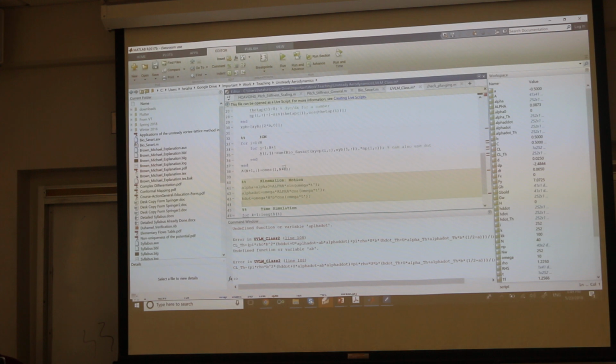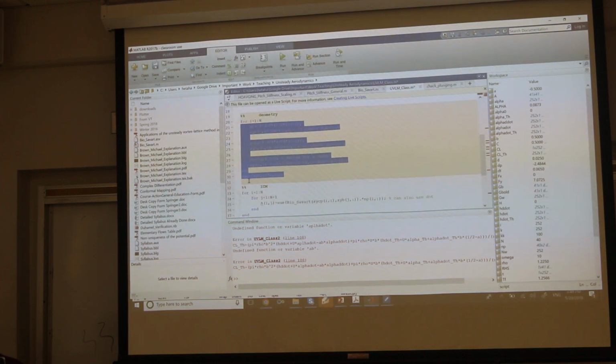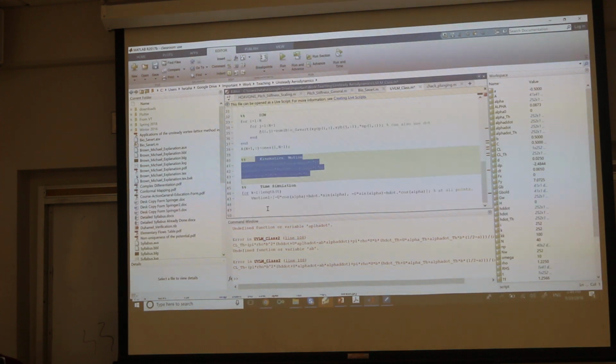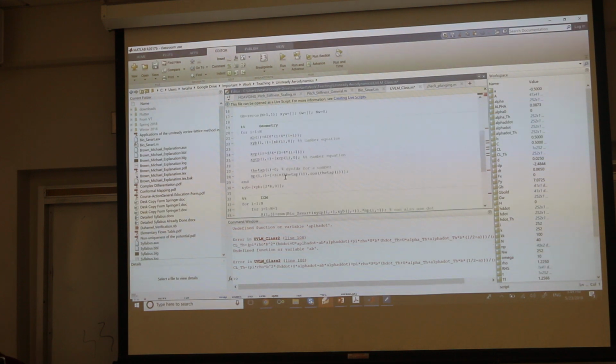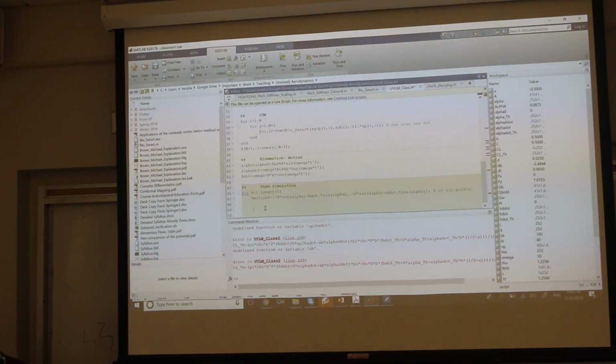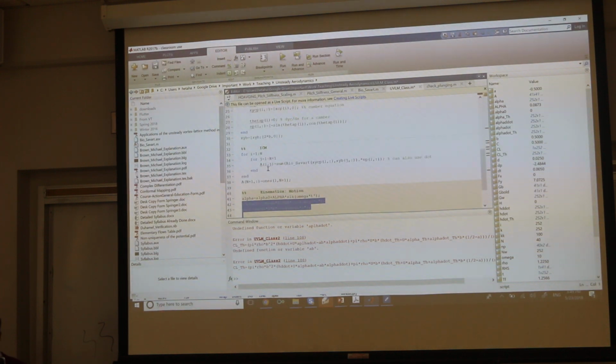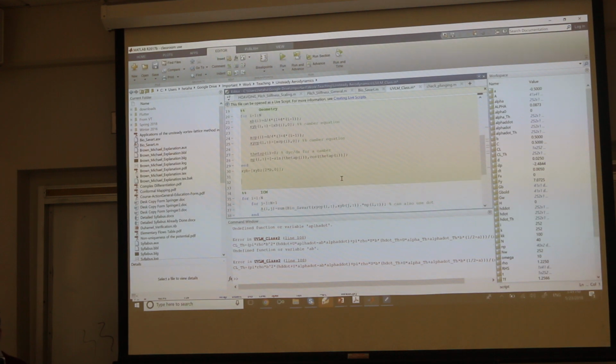Okay, we're done with initialization. We have geometry, we have the influence coefficient matrix, we have kinematics. You might want to check before doing anything, so let me even do this. Let's check our mesh. Let's plot, say, we have a plate, so the x is between 0 and 1, and the y is zeros. This is my plate in black.